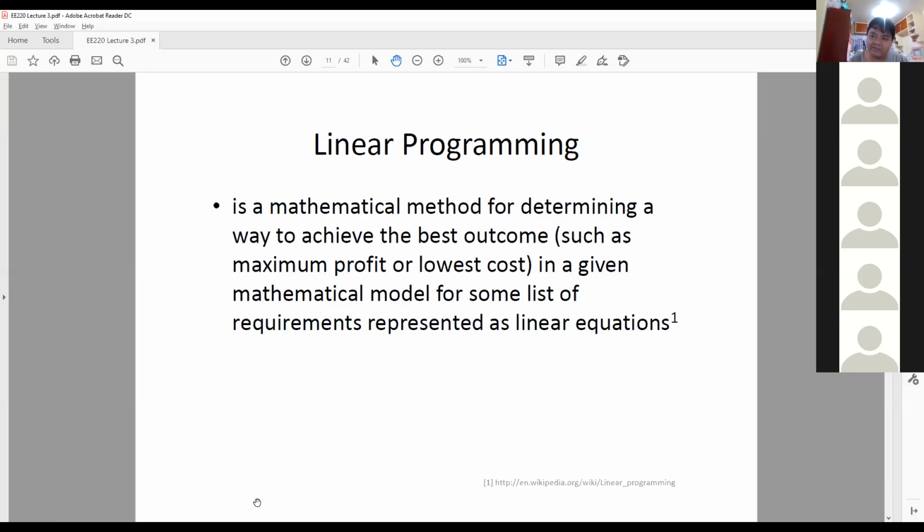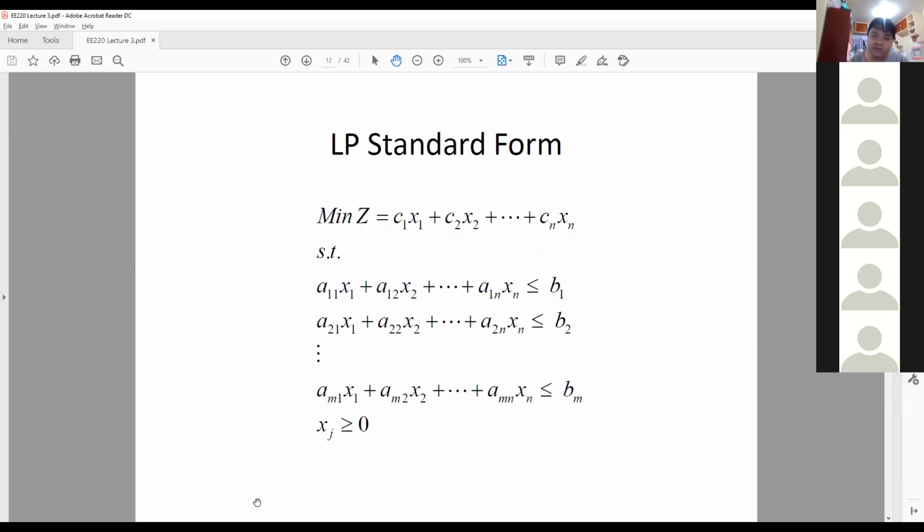So, pagka kunwari, like sa Philippines, we have hundreds or almost 1,000 buses. Medyo mahirap nang i-solve yun, no? Napakahirap na. That's why we're resorting to some simplifications like linear programming. Okay? So the LP standard form is that you have a cost function where it says, let's say yung Z is your cost function, and that will just be C1. Isi-simplify pati cost ng generator. Imbis na quadratic, gagawin mo na lang rate. Parang yung katulad ng example ko, 4.1 peso per kilowatt hour na lang yung buong equation na mahaba.